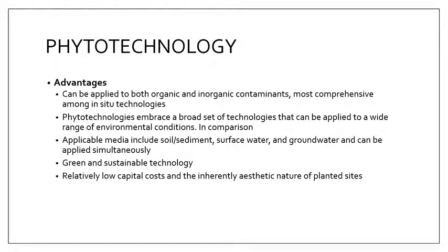The advantages of phytotechnology in general: it's the most comprehensive among in situ technologies because it can be used on both organic and inorganic contaminants. So it can cover a lot of types of contaminants, and it can be applied in a wide range of environmental conditions. You can use it in the redox zone, in the capillary zone, in the groundwater. And it also allows simultaneous treatment of those zones.